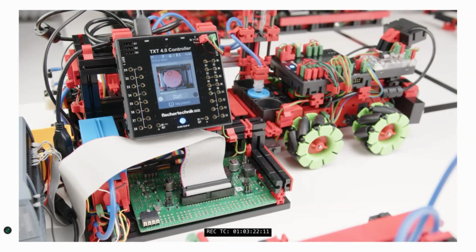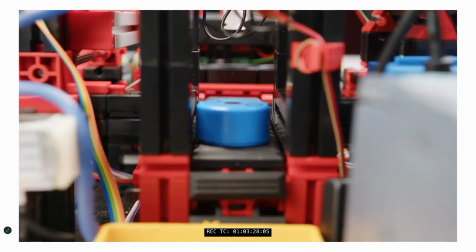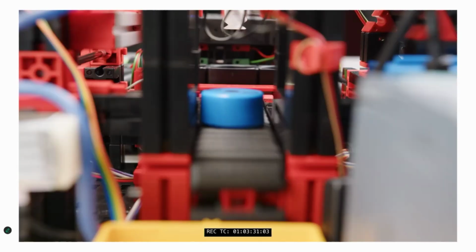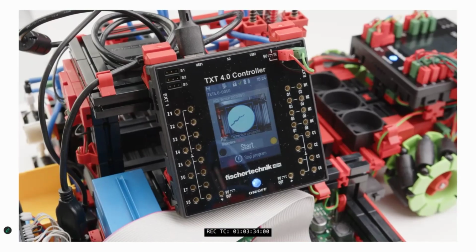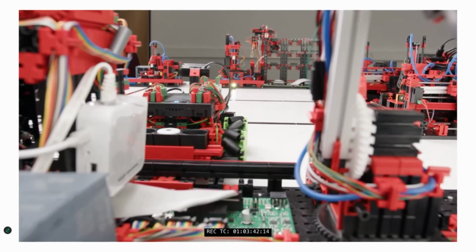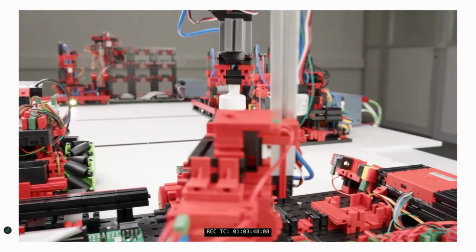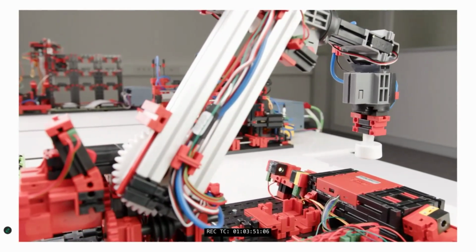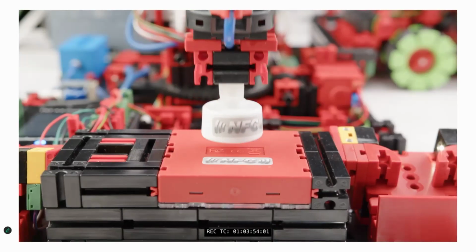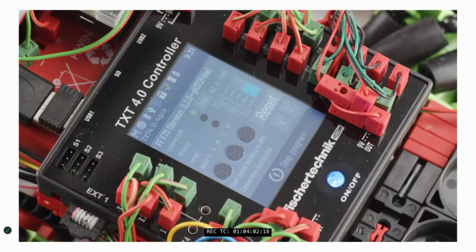Again, like before, the vacuum gripper at that station picks up the workpiece from the AGV and puts it onto the conveyor. In this case, it's scanned by the camera, and it's classified depending on whether it's defective like that one, in which case it's rejected, or otherwise it's put back onto the AGV for movement to the next workstation or for storage. In this case, it goes to the process where it's again scanned, that everything has been done, and it's ready for pickup. And here you have the AGV going to recharge.